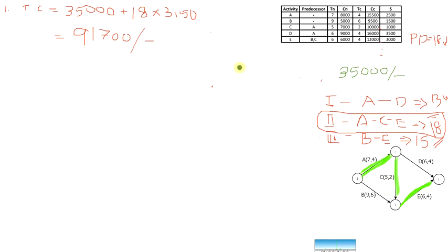That is, if we can reduce an activity's duration by 1 week, we should supply materials and resources with the minimum cost involved, so that the total project cost will be an optimum cost. So we have to select an activity with the minimum crash slope.